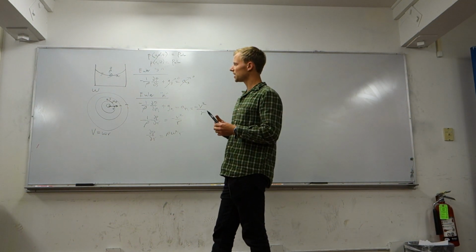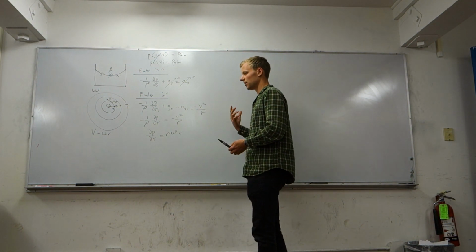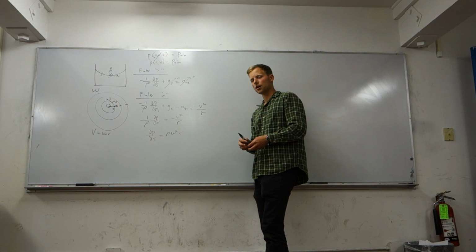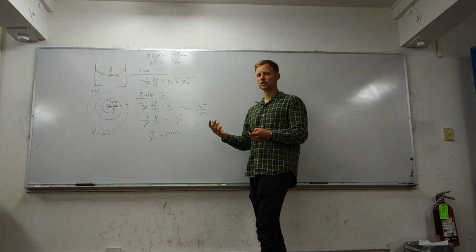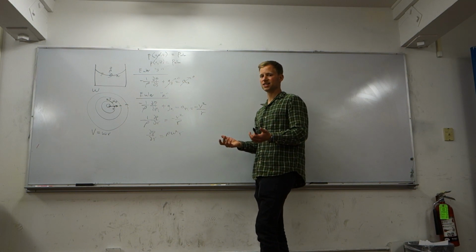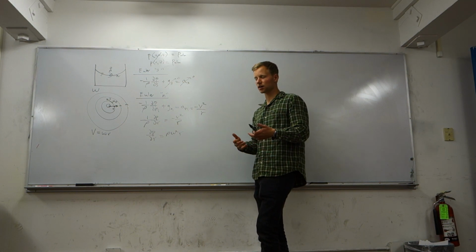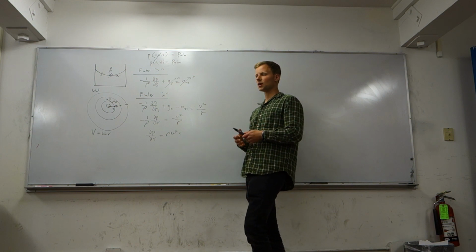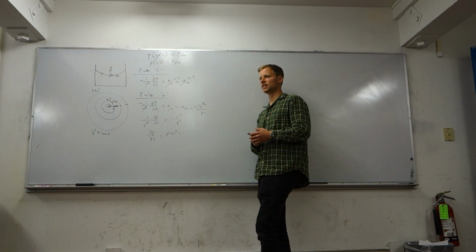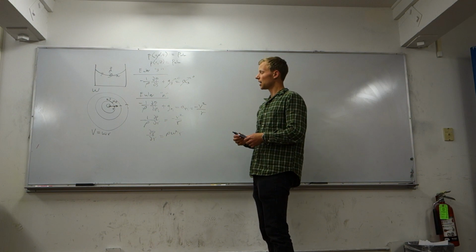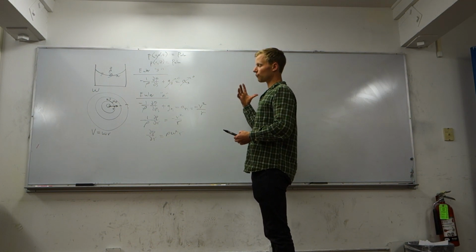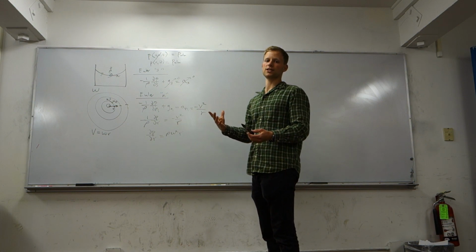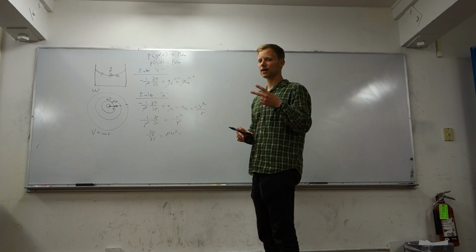So rho gh, if you recall, comes from the hydrostatics equation, which gives us the integral of negative rho g dz, which gives you a p naught plus rho gh, or minus rho gz, depending on the coordinate system. And that itself is a formulation of an Euler equation. So you can think of doing this 2 ways.